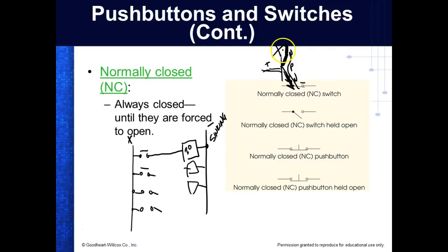We hook up the NPN, and this is what we keep up with them, that arrow right there. We look at this arrow right there, and this is not pointing in, right? We look at this arrow right here, and it's pointing in, and that's the symbol. But you don't need to know that. All you need to know in this class is that if they don't specify a sinking sensor or a sourcing sensor, an NPN is a sinking sensor and a PNP is a sourcing sensor. That's all you need to know in this class, just if you needed to buy a sensor, right?